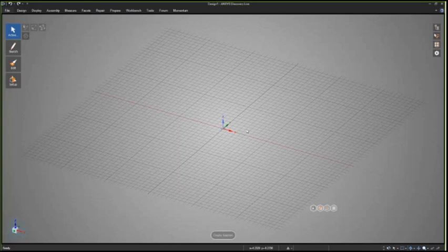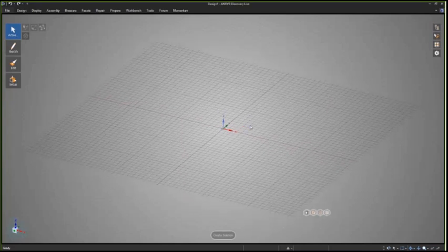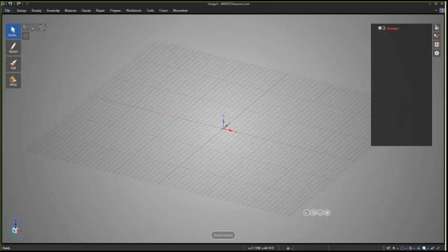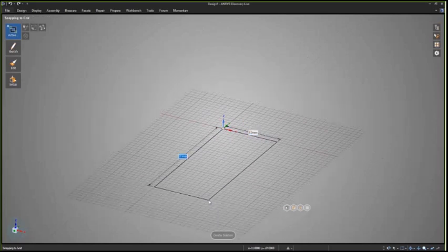I know a lot of you may be familiar with feature-based CAD tools like SolidWorks to create your models, but Discovery Live and Discovery SpaceClaim do it without features. There's no feature tree in SpaceClaim, which means I can edit parts from any other CAD system. I can open up Parasolid and Step and SolidWorks and edit them pretty much in a similar way to how I create them. The difference with Discovery Live versus SpaceClaim is you could have simulation running while you're designing.